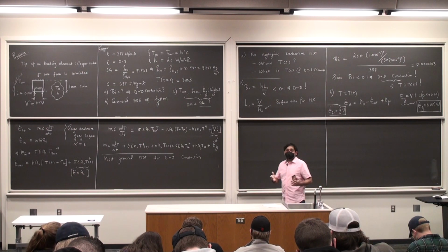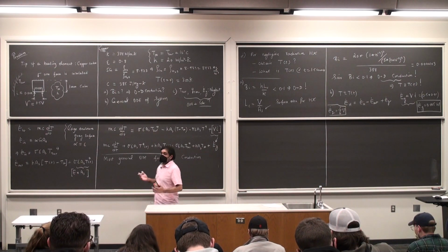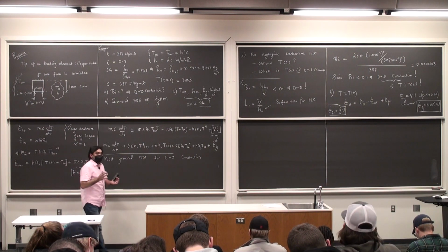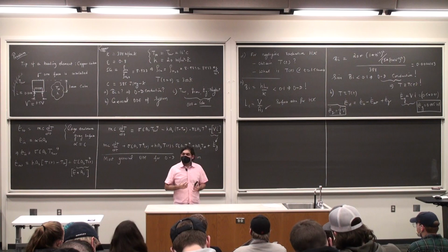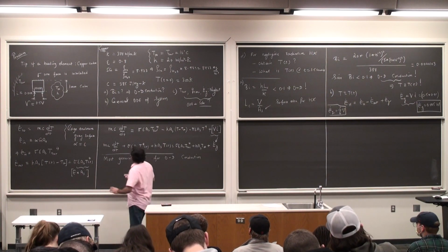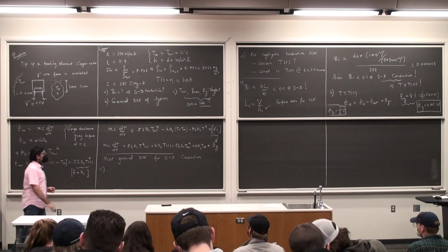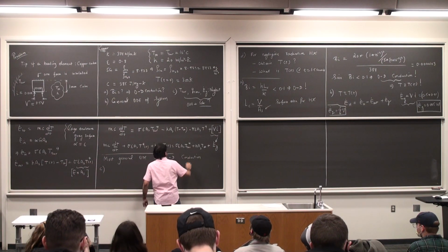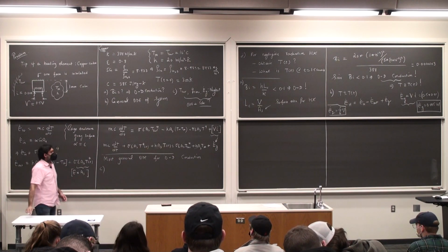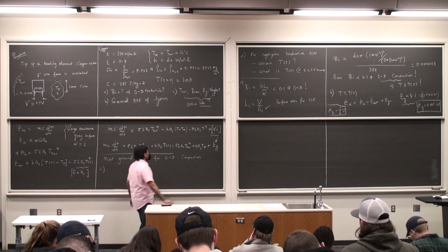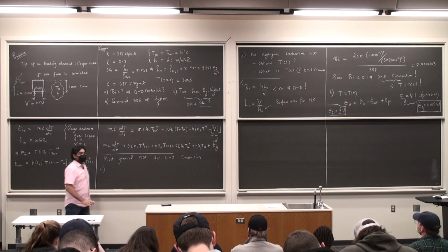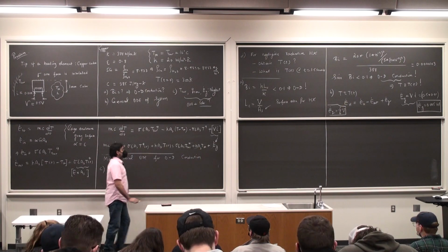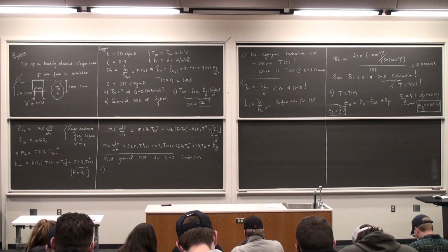I'm going to ignore convection, I'm going to ignore energy generation, and we're going to say that the surrounding temperature is negligible, so the irradiation from the surrounding is fairly minimal. But there is still some amount of emissive flux coming from the copper element itself, so that will be included. So that's my third part of the problem, so that's part C. If I do the following, take a look at the general ODE. I'm ignoring convection, so those two terms cancel off. I'm ignoring energy generation, so the last term drops off. And then I'm ignoring the surrounding temperature. This is once again an order of magnitude analysis. So that also drops off. And so I'm left with the following ODE.